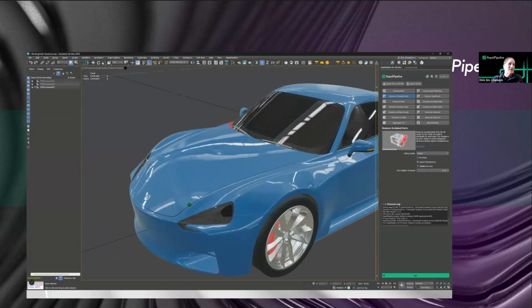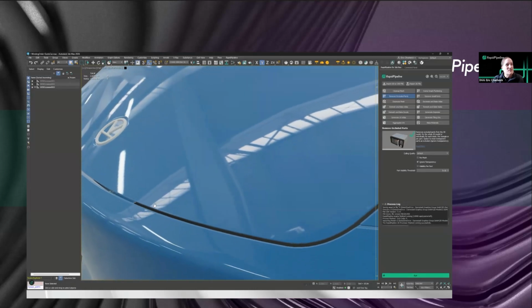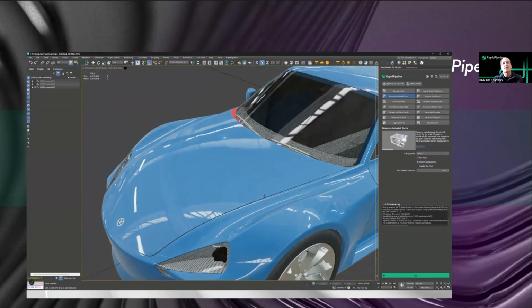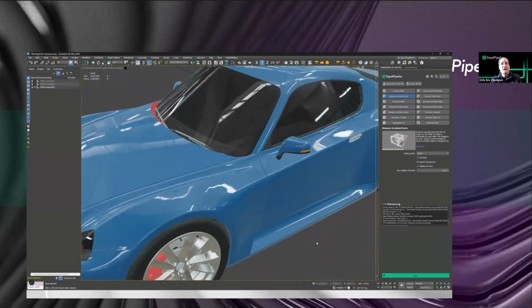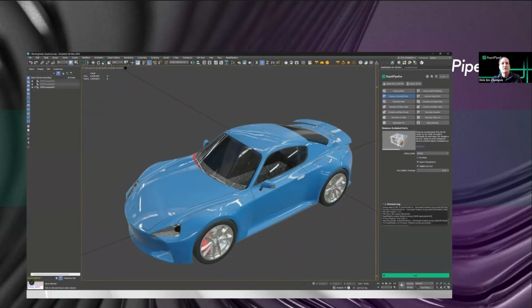This surface here, for example, has some fine cracks in the hood, so you can see some triangles back there and not see others. So I generally like to have it remove whole parts, which in 3ds Max speak we would call elements in a mesh. I don't want it to remove individual triangles because then I end up with some floating triangles inside the model. While being physically correct, I don't really like that as a 3D artist. I'd rather have it remove whole parts, and that's what that option does.